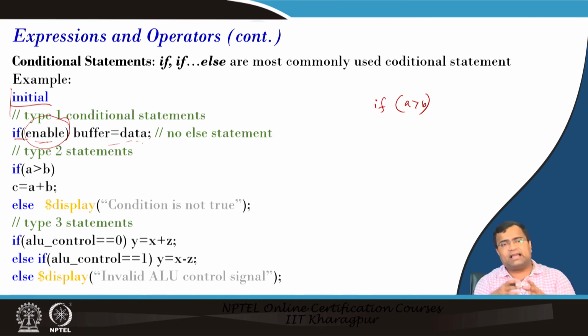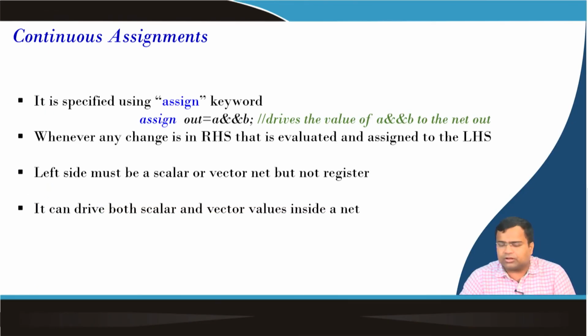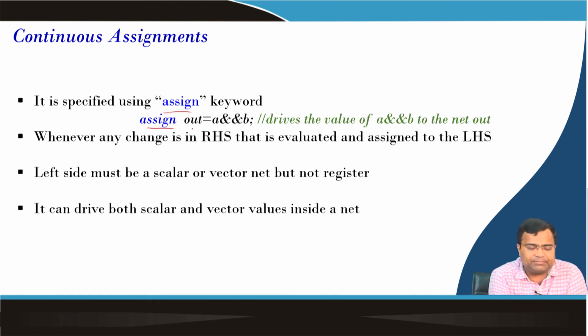So this if and else statement is similar to high level languages like MATLAB or C, but we should try to avoid using such if-else statements or high level language as much as possible, because we want to see the actual hardware architecture. But when that is not possible, we need to mix between high level, that means behavioral modeling, as well as structural and data flow modeling. So for continuous assignment, if we go for data flow modeling, we will write an assign statement.